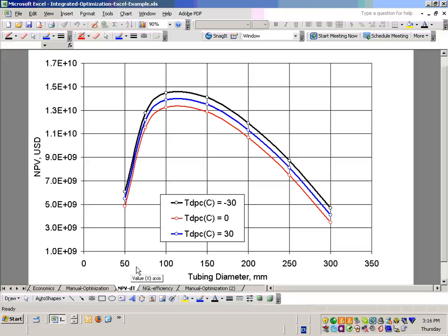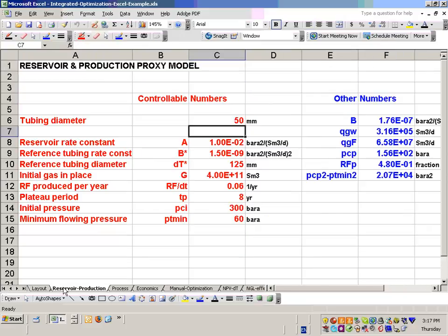What would be nice is to find this optimum automatically, with the optimizer. Because as soon as we change anything, we have to go back through this process, copy and paste, plot. It's going to get old. You guys are pampered. Do you realize that the industry doesn't do this at all? Because the single change that you make here, tubing size, is an exercise they might look at manually once or twice. You'd have to rerun simulation models, go back to Prosper, regenerate the tubing tables, rerun the simulation models, pass all the information to the process group. It just doesn't happen.